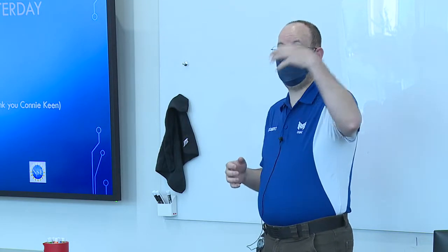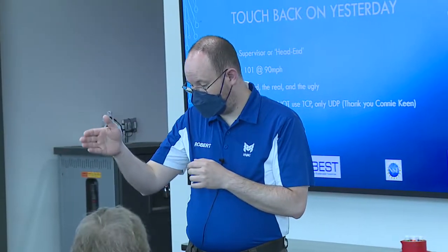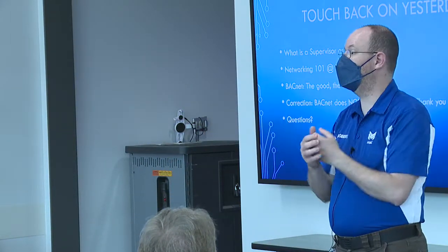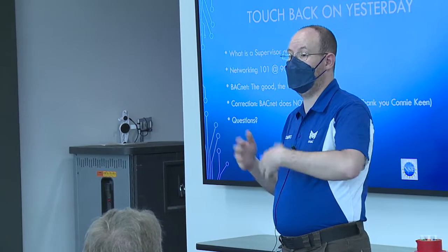The setup that we have, I'm not going to lie, is ugly. But it is also a realistic setup within a building controls network if you have to run your own network. At each table, for each 2 participants, we have a 5-port network switch. You could imagine one of those sitting in each of your control cabinets throughout a building. Then running down the middle of the room, we have an additional 5-port network switch. This would connect back to a more central point on a floor maybe, and connect to the other floors.